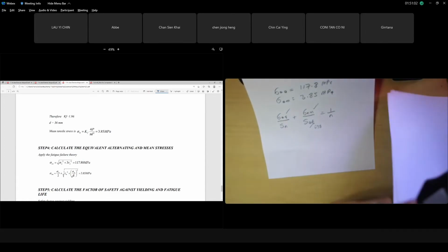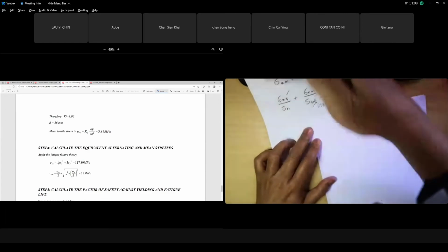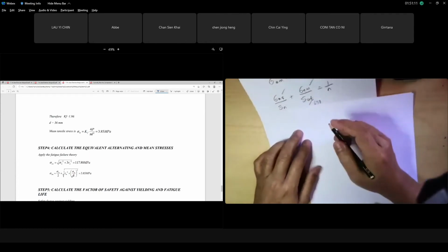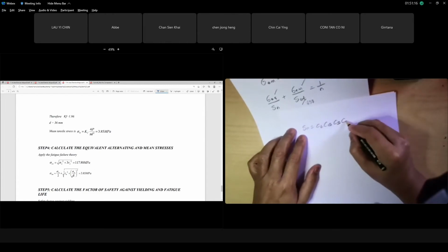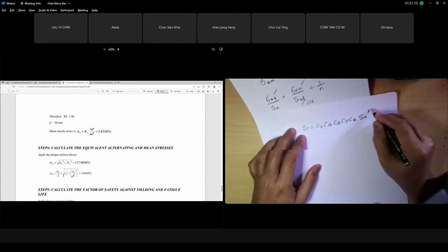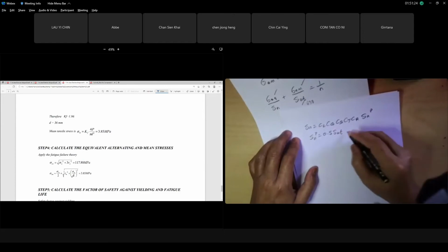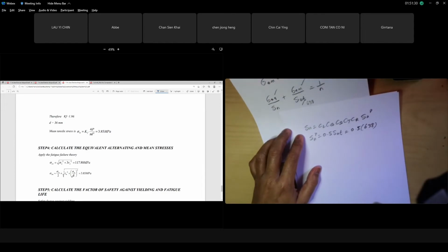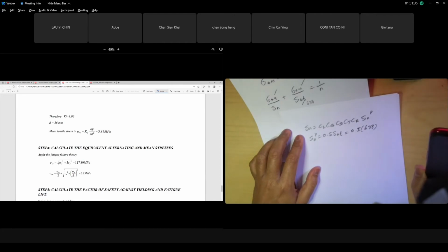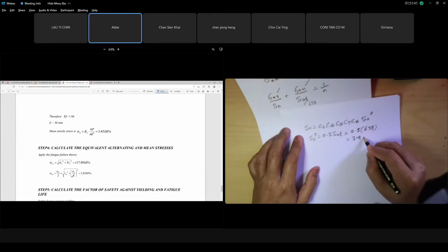Okay, why is SN? SN is your endurance limit. Actually SN you can calculate earlier just now, tapi depend on your approach lah. Yang ni I solve ini dulu, then only SN. So, okay, clear you me, you see my video. SN equal to CL, CG, CS, CT, CR, SN prime. Okay, we know SN prime is 0.5 SUT for steel lah. This is only value for steel lah. 0.5 of your 638. So it will become berapa? Calculate, saya punya calculator saya ada, phone saya guna untuk webcam lah. Calculate for me. 319, Doctor. So this S prime is 319 megapascal.